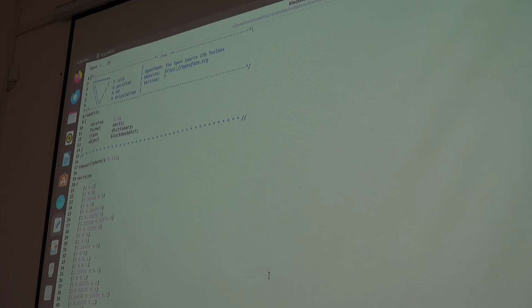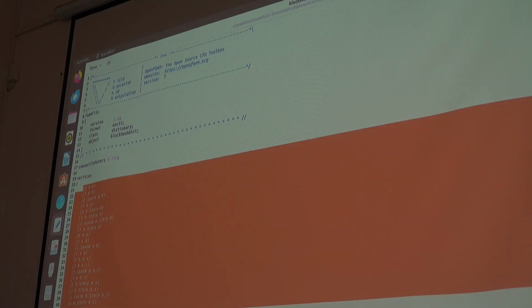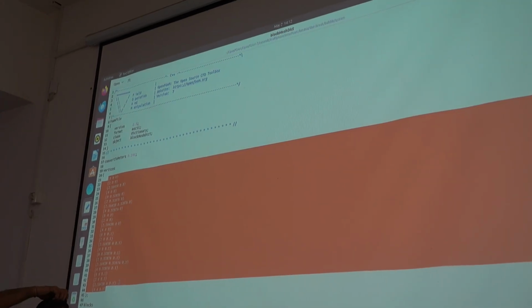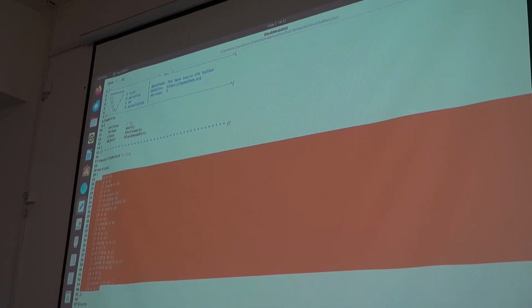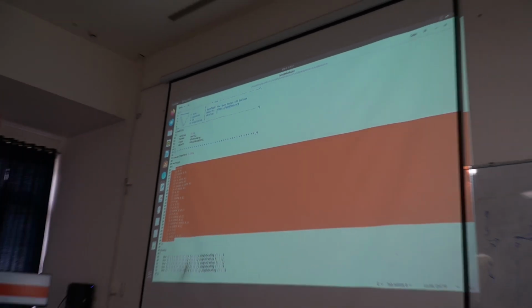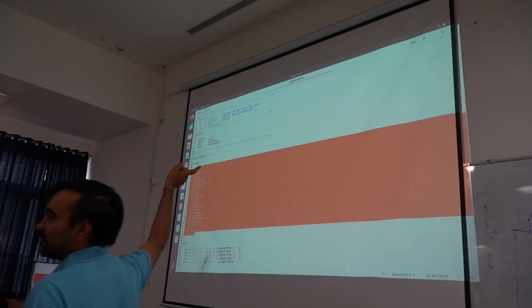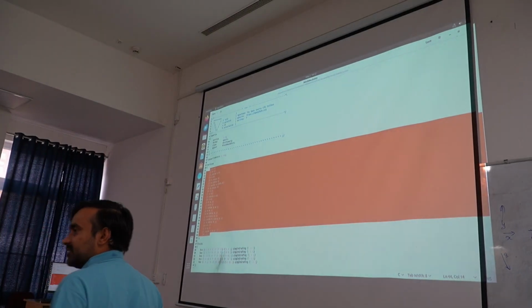After entering into the blockMeshDict, what you need to do now, you can see in this vertices command, there are these, I have highlighted over here. These many points are given. In place of these points, you have to give the 6 points which I have specified on the slide. Okay.